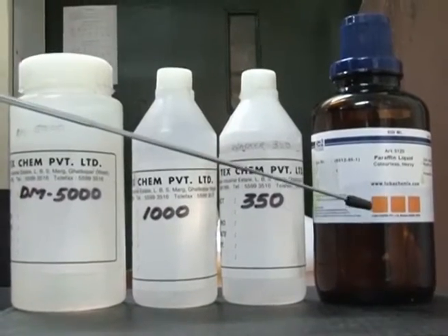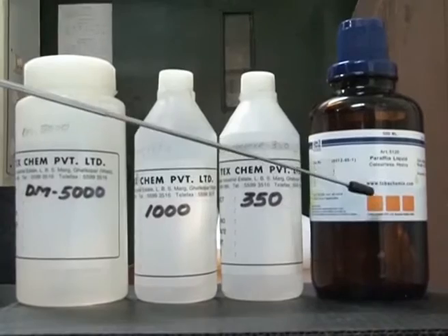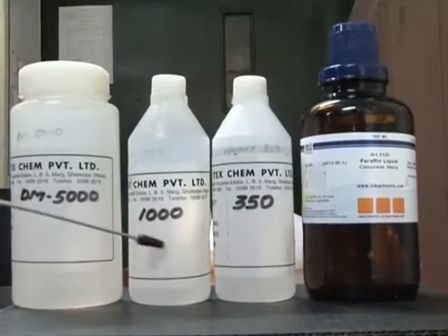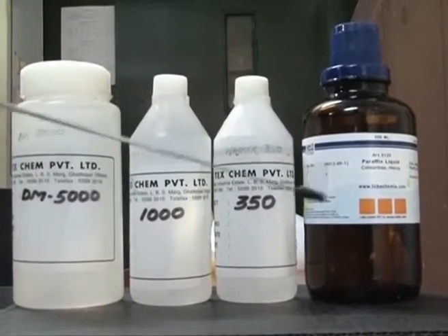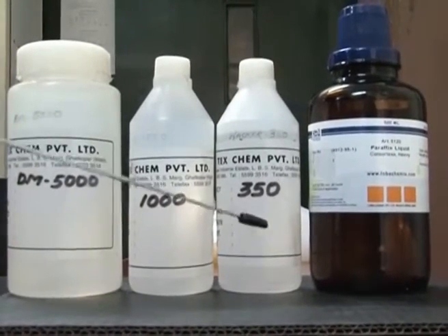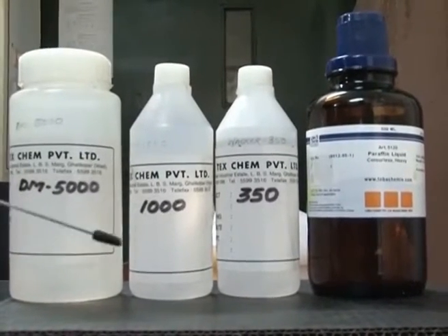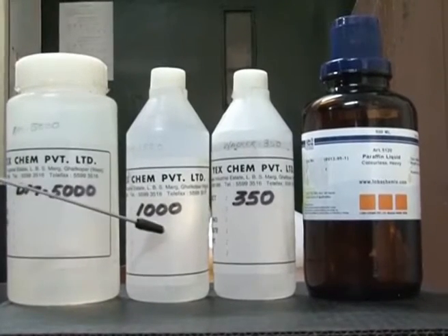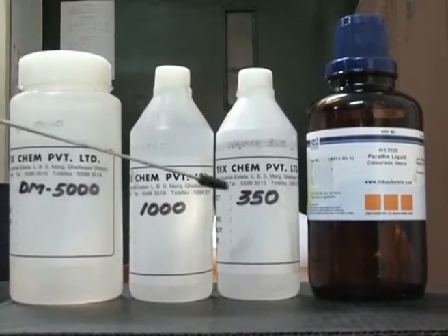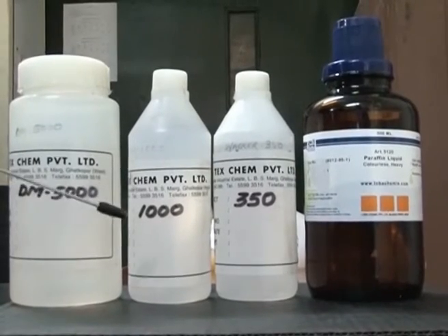The second major ingredients in the polymer rheological medium is rheological additives. In the rheological additives, we have the plasticizers. These are all the plasticizers with varying viscosities. This is the first plasticizer, that is a paraffinic oil, and these are the second plasticizers, a silicone oil of different viscosities. You can see the 350 centipoise, 1000 centipoise and 5000 centipoise. This is the high viscous silicone oil and this is the low viscous silicone oil. These are the plasticizers in the present process of making the medium.